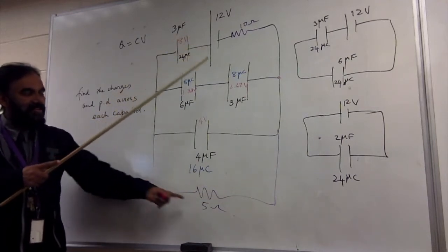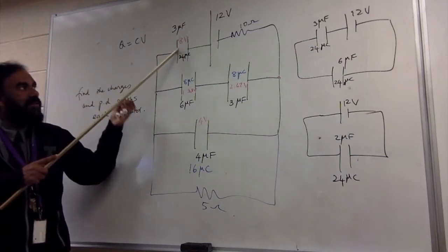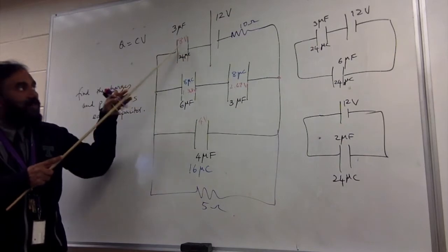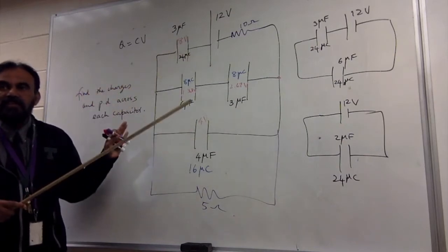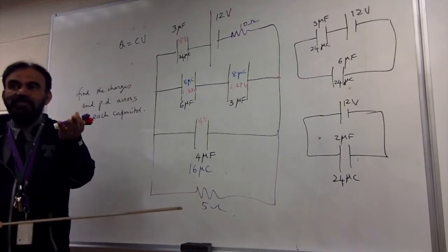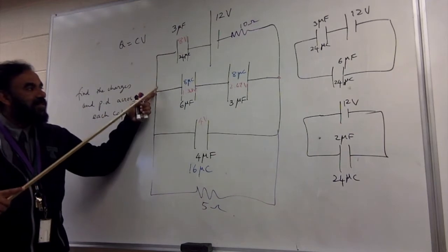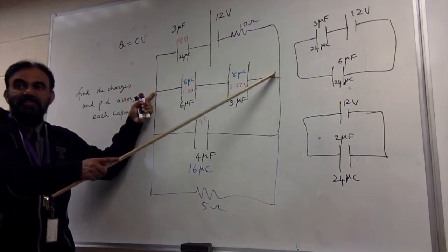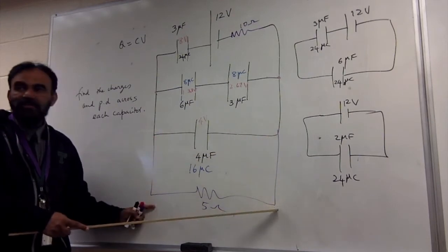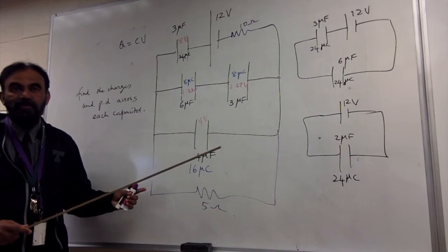And that drainage is going to slow down because this voltage is going to pick up from 8 to 9 to 10 to 11 to 11.9. It's going to continuously pick up as long as there's current. And this will actually grow to 12 volts. When this grows to 12 volts, what's the potential difference here? 0, and here 0, and here 0, and that's when everything comes to a halt. So no more current will flow.